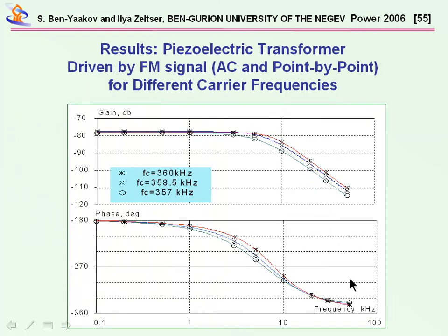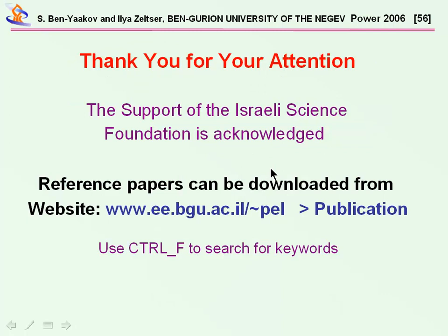A feature which I've already mentioned is being able to look at the small signal response. This will be between the output and the frequency modulation. What we see here are straight lines which we got from the envelope simulation method, and the dots were done cycle by cycle with the full circuit, and of course the agreement is very good. This actually brings me to the conclusion of this presentation.